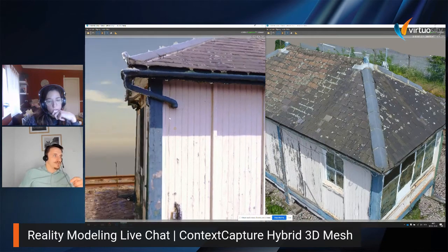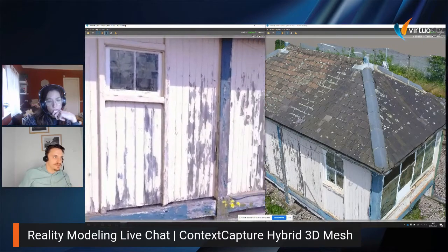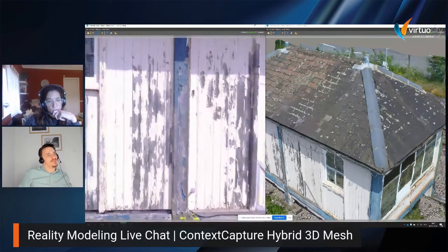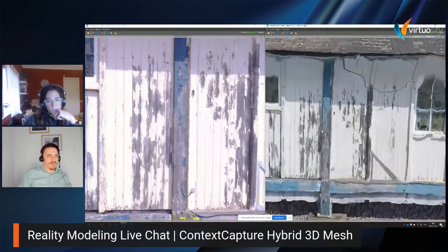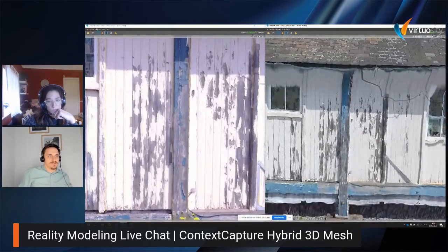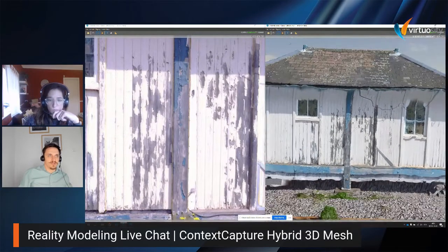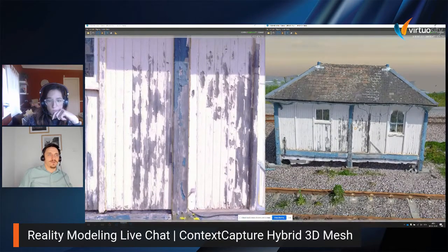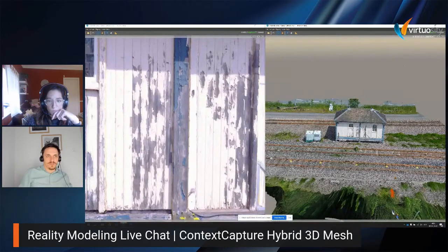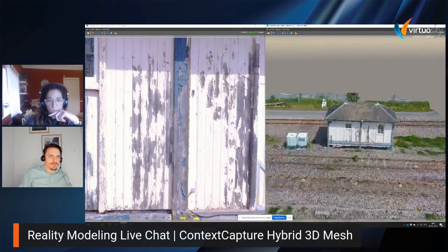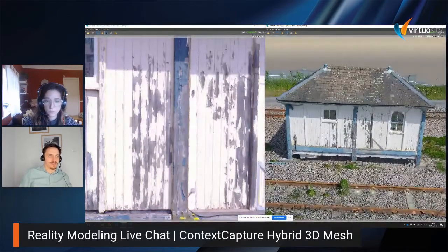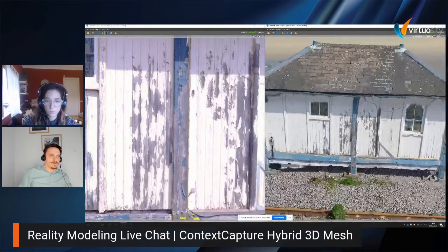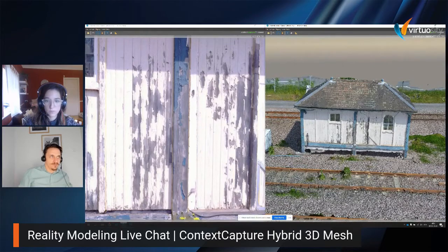At the left we can see a result. Let's take those scratches here. They look not bad, okay, but we can see that we don't have that much sharpness. Take a look now on the right side. This is taken from a drone picture. Looks okay. If we would take the same but closer oblique pictures, because this example has been taken by orbiting in the air, so we are mostly focused on the roof here, but if we took oblique pictures from the ground, we could gather a lot of information about the texture, and then we would have a much better result coming from the photogrammetry.